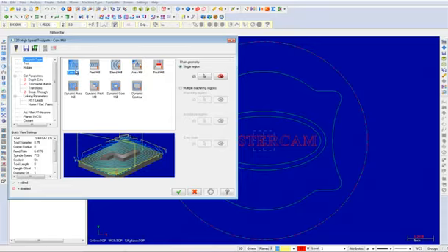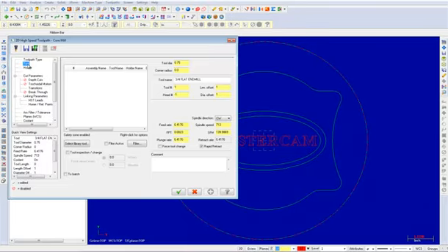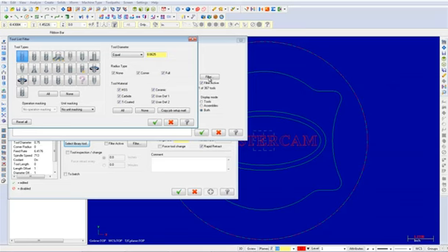We will now select a 3/4 inch flat end mill from the tool library and set the tool parameters. From the Tree View list, choose Tool. From here, click on the Select Library Tool button and then the Filter button. Select the None button and then under Tool Types, choose the flat end mill icon. Next, under Tool Diameter, pick Equal and input a value of 0.75 as shown.